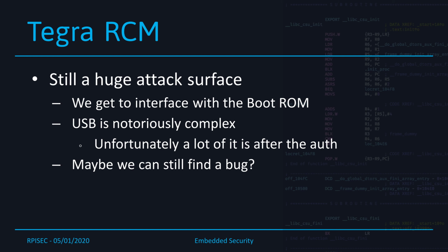Okay. Yeah. So even with the commands being signed, and this limits a lot of the functionality that we can interact with, we still get to interface with the boot ROM in some way, because you have the whole USB stack essentially, which is a notoriously complex networking-based sort of stack where you have different nodes and endpoints, and there's all this complexity going on, and it's essentially this huge attack surface that interfaces with unknown devices, and it's unpatchable, which might seem like a bad idea if you're a manufacturer, but I guess you have to consider the trade-offs of having the devices be either fully secure and completely unrecoverable, or be actually repairable in the case that the software is corrupted. So maybe we can still find a bug.